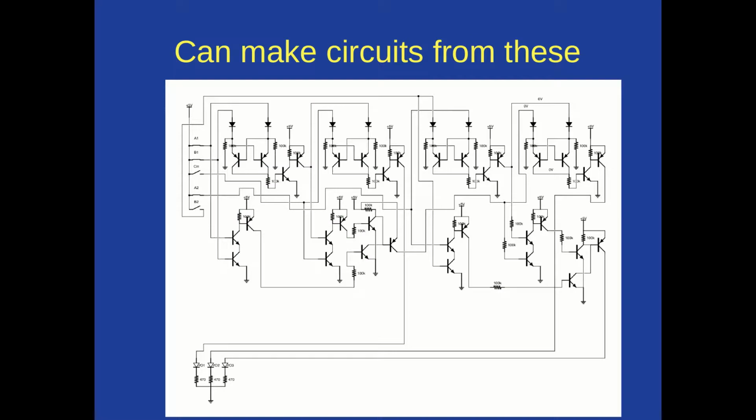And so we can design circuits using transistors. So each of these little funny-looking symbols, that's a transistor. And the squiggly lines are resistors. If you've taken Engineering 120, you know what a resistor is. These are LEDs, so for output devices. And this is a 2-bit adder. So it lets you put in 2 numbers, each number between 0 and 3, and it produces a coded representation of the sum on these 3 lights. So if you've done 250, you've built a 2-bit adder, and your circuit was probably simpler than this, right? Because designing with transistors is fairly cumbersome.